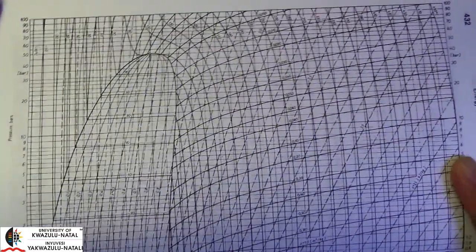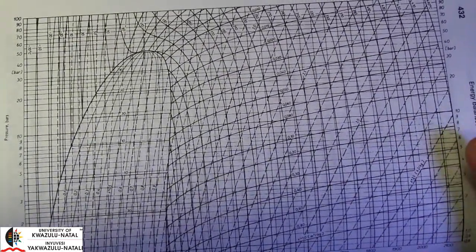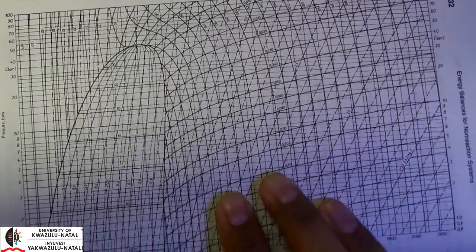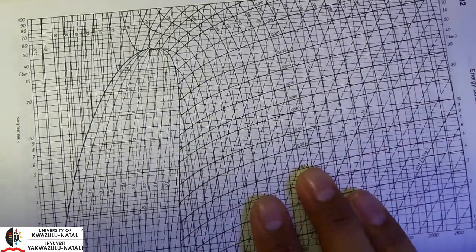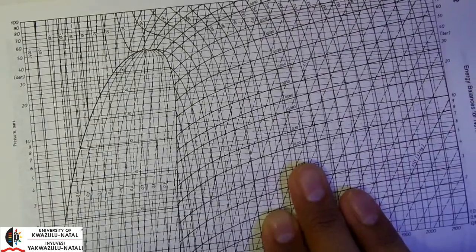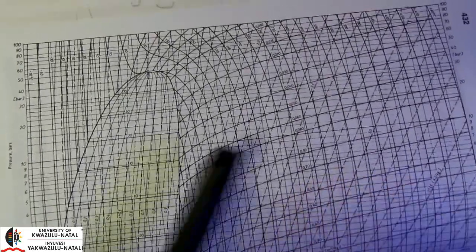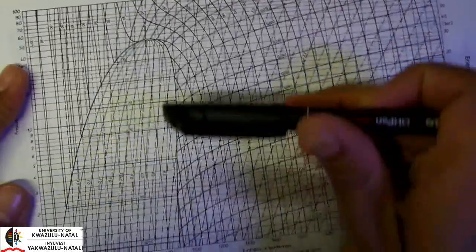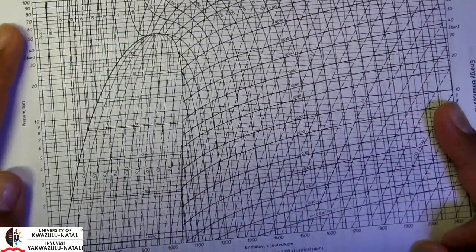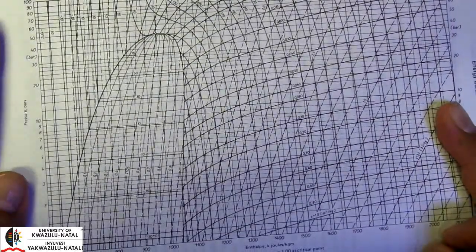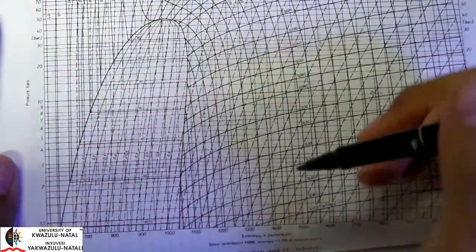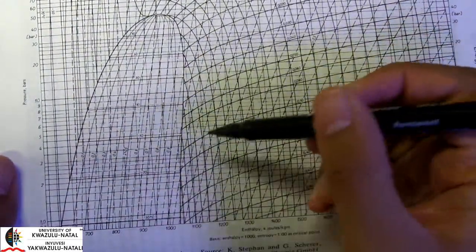But for now, what does the degree of freedom analysis have to do with enthalpy and our energy balance? Well, we can, of course, obtain various relationships between our pressure, temperature and enthalpy in order to determine our points of phase transition and our associated enthalpy required to accomplish these phase transitions. Okay, so this particular page that you're looking at is a pressure enthalpy diagram for propylene.